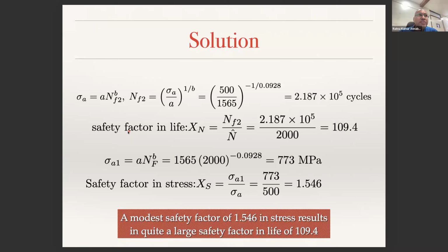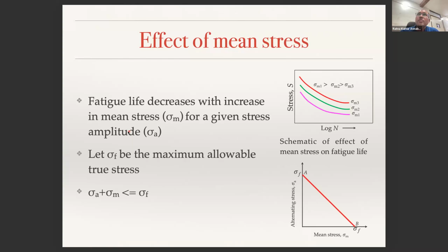In today's class, we will look at what happens when you have non-zero mean stress. That means the loading is not fully reversed, but something else. As you increase the mean stress, over and above your fluctuating load, there is some constant load acting on the component.